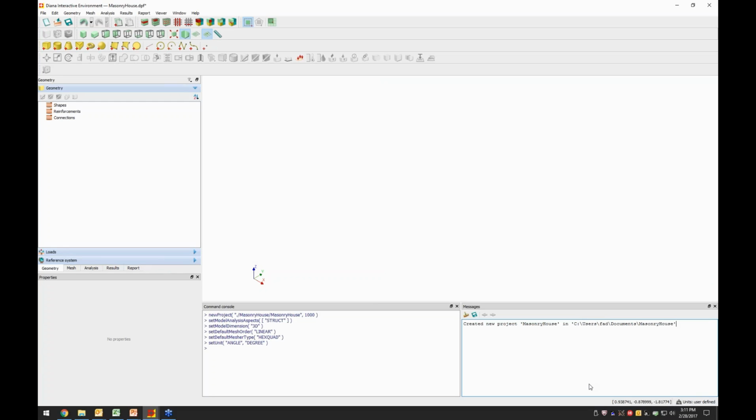So we start the geometry definition by making the lines of the walls and extrude them. I will define separately the walls in X direction and Y direction. I will need this because of the orthotropic parameters of the masonry model. I will come back to this later. So I will start by creating the lines for the walls. So let's start with wall 1 in X.